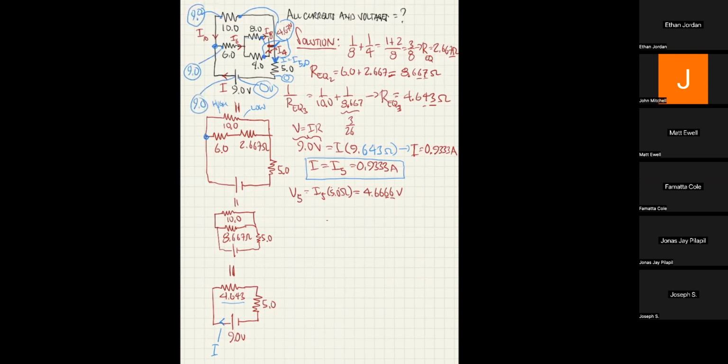Remember, we're supposed to think, well, you didn't have me for lab, but I did try to explain it in class one time. What you think of is each battery is like a set of stairs or a water pump or something like that. So when you go in that little wire from the 5 ohm resistor all the way up to the short side or the negative side of the 9-volt battery, that's all the same elevation. We'll call that ground level because it's going to be what we call 0 volts, as I already showed you with the bubble. And then I'll take the stairs from the short terminal of the battery, which is the negative terminal, up to the long terminal, which is the positive terminal. And now I'm up at a height of 9 volts.